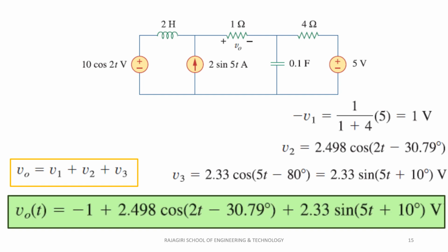Summarizing the topic, we have seen that the superposition theorem provides a method of determining the voltage across or current through an element in a circuit having more than one independent source. Even though the method involves analyzing a larger number of circuits, that is, n circuits for n independent sources, all the circuits are greatly simplified compared to the original circuit.